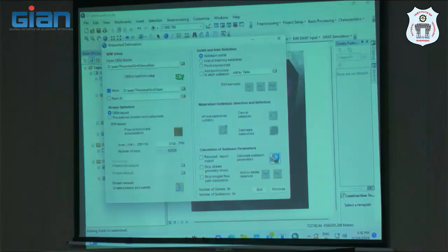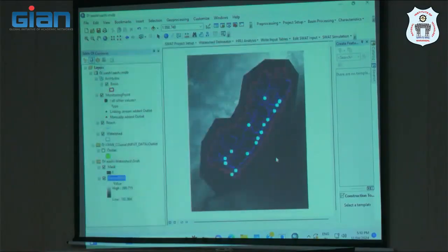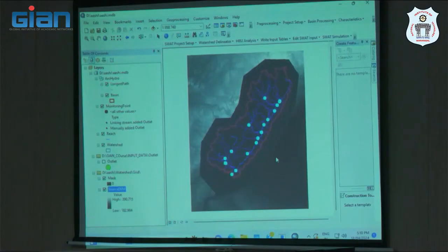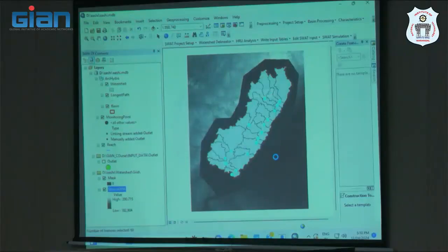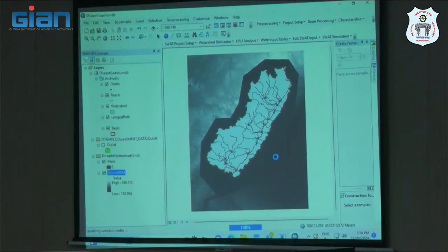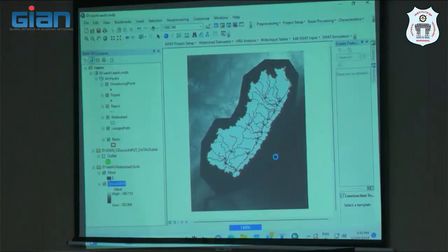That will get simulated. Yeah. Without even check. What is the second instance? If you are adding an inlet or getting watershed, whatever watershed area that drains into that particular point will not be simulated. You need to provide input at this particular point. And downstream, again, if one secondary or primary stream is joining before the delineator, then the discharge from that stream will be simulated. It has to be simulated.